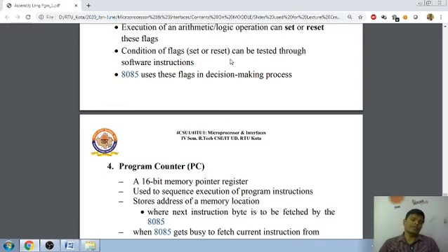Checking the flag registers will be difficult. So since you are home now, you can download the GNU simulator of 8085 and try to execute some instructions, and meanwhile you will be able to check different ports' results. If you are redirecting some output to a particular port, then you will be able to see the port's content at the completion of a particular instruction. Then again, here we can see the result of each and every flag separately.